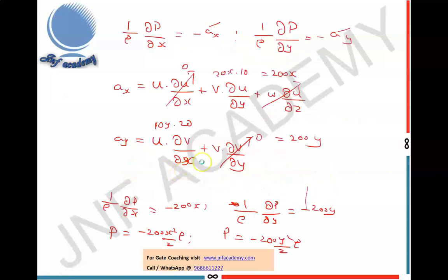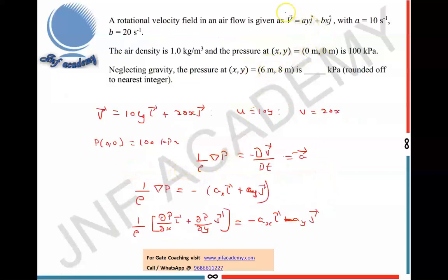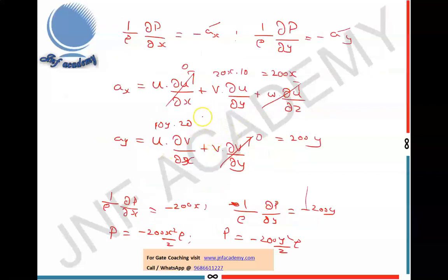How they have given the velocity function of the flow field. So this was the velocity function of the flow field, right? Now using this velocity function of the flow field, using Euler's equation, because it's a field function, right? It is not along a streamline. They have never mentioned anything like that. So we use the differential form of the momentum equation, which is Euler's equation.